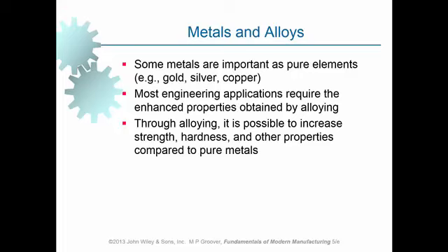That is very strong, and it is still highly conductive. Of course, when we are adding another element like copper, which by itself is a conductive metallic material, the conductivity of silver will be sacrificed, but not much, just a little bit. And it is worthy of adding this much of copper to it in order to improve its strength significantly.